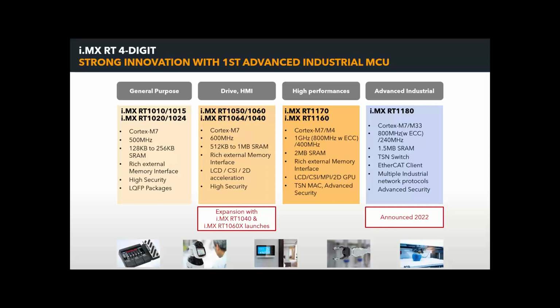We also have a very rich, your typical, MIPI interfaces, since most of the RTs are flashless. That gives you a very flexible and quick interface with external flash to achieve top performance. And we also have a rich peripheral integration, your standard, essential peripherals that the MCU would have on the RT1010 or RT1020.